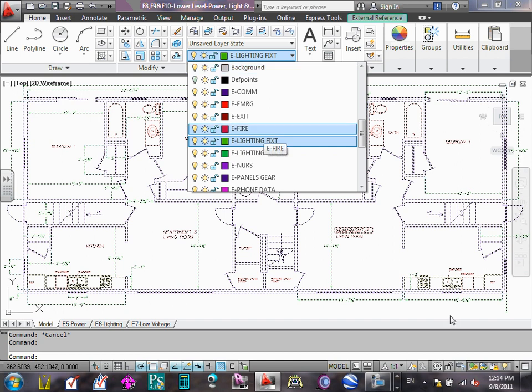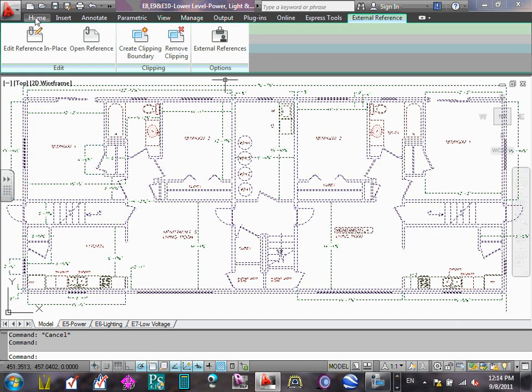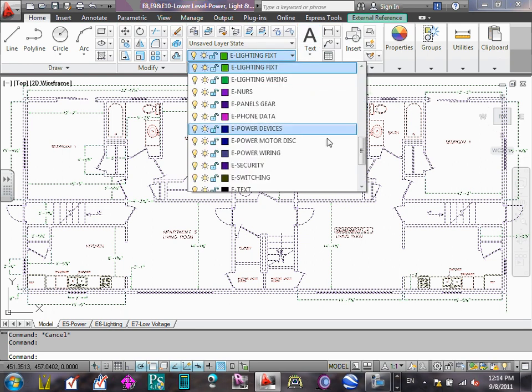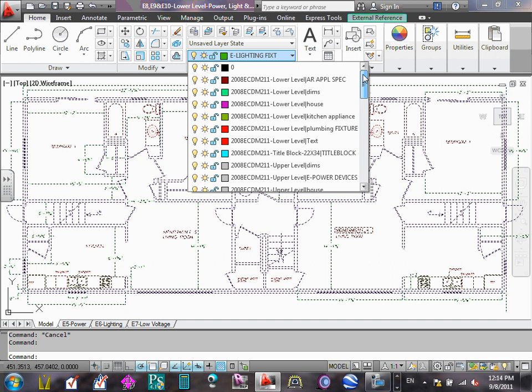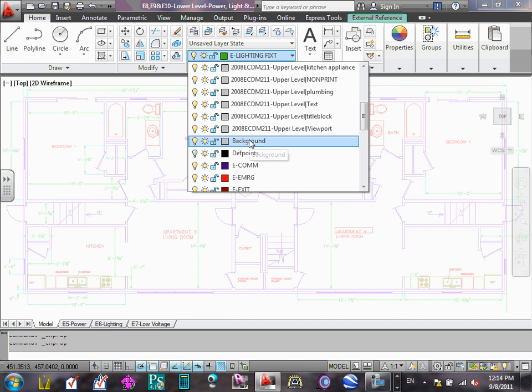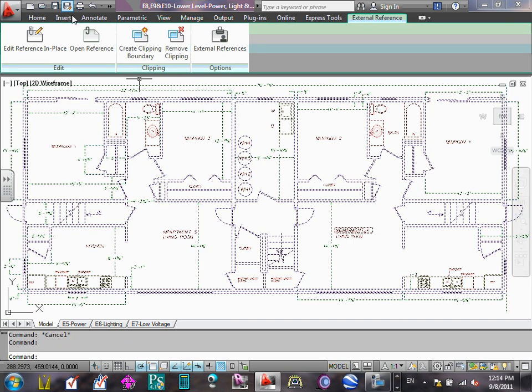So one more time, let me repeat. Click on the stuff that you picked. Go to home. Click on the layer here. And make sure you put it on the layer number, which layer? Layer number background. Everybody's okay with that, guys? Cool. Now my layer is a background.